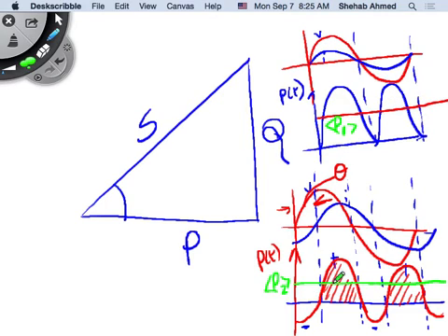Now some of this voltage and current is creating this power that is going back and forth. So this is power coming from my source, and this is power going back to my source. Power coming from my source, power back to my source, right? And this exchange of power is what is called reactive power. So there's average power, there's real power, which has this average value here. That's the real power. Real power is what creates torque on a motor shaft. Real power is what we use to light up the lights, right?